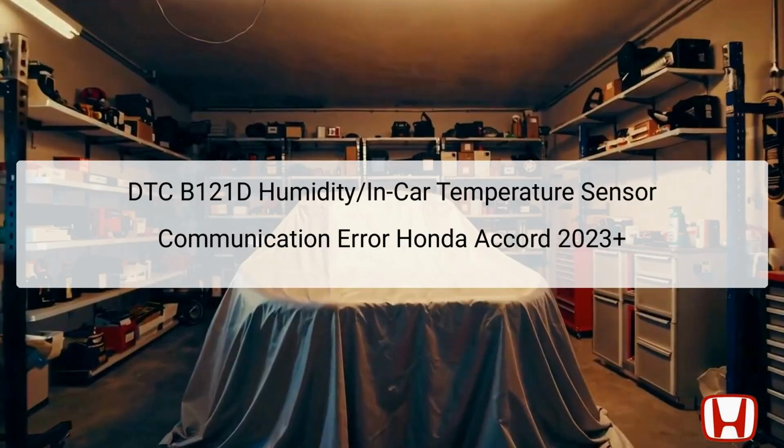Welcome to this troubleshooting presentation focusing on DTC B121D, which indicates a communication error related to the humidity and in-car temperature sensor in the 2023 Honda Accord. This diagnosis becomes crucial when the climate control unit fails to receive specified data from the humidity in-car temperature sensor.